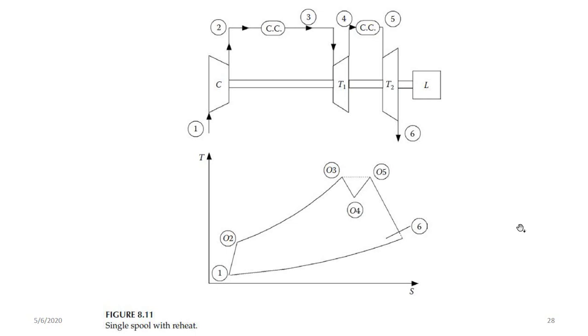That would be a serious disaster, which no engineer would want his name attached to. So you need to make sure that the maximum temperature entering the first turbine is the same as the maximum temperature entering the second turbine. That's why on the TS diagram, you can note T03 is equal to T05. From here, you can tell.